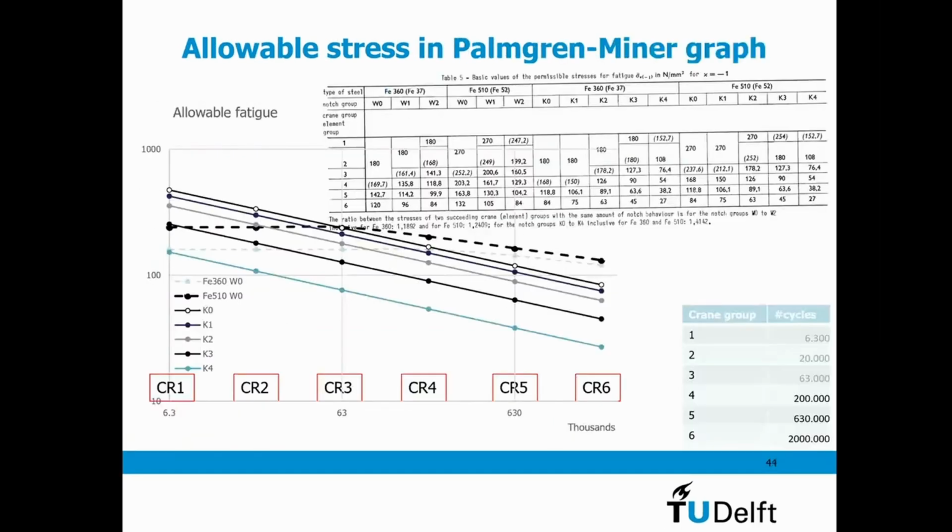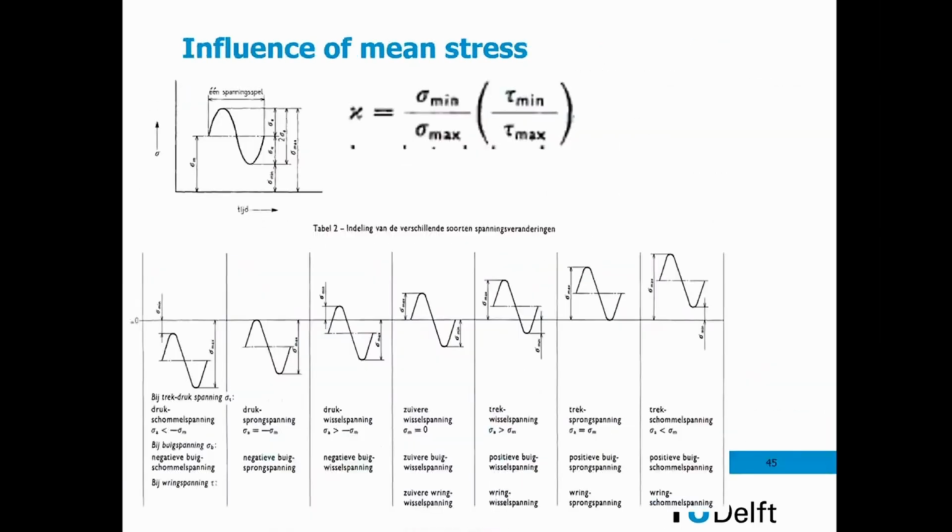What do I have this curve? Yeah, here. So they take into account also some kind of a kappa value. So since they want to use only one limit, they want to calculate the maximum stress and the minimum stress over a lot of load cases for every point. And they take these two values, and based on that, they see, okay, is it a varying stress or not? And does it change sign or not?